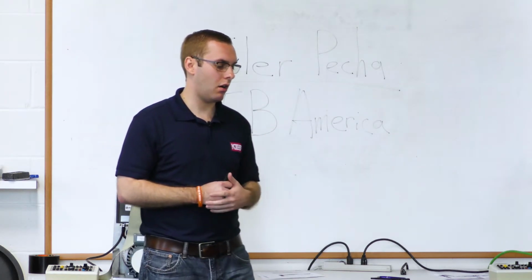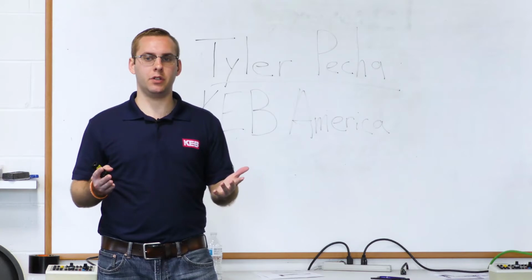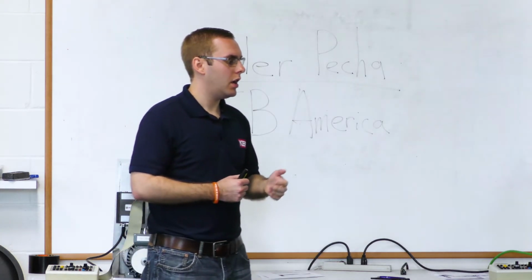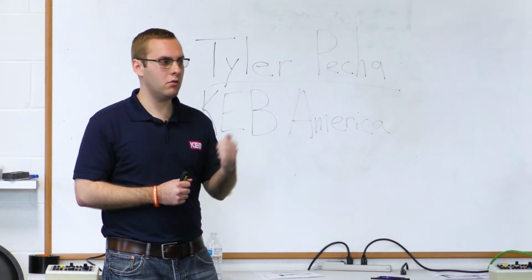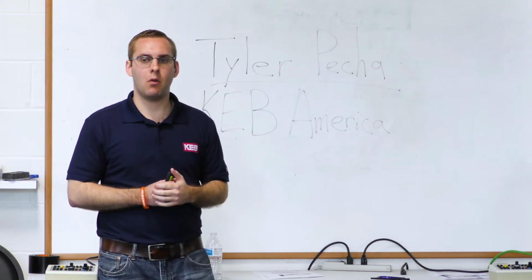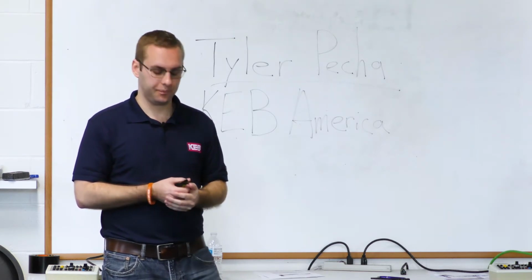And if they're just using our 5 volt supply, if the encoder is a long ways away, you might have just enough of a voltage drop where there's a power issue. So one thing you can do is we actually have 15 volts available on the encoder card. You can hook up the incoming power for the encoder to that and see if the error goes away.